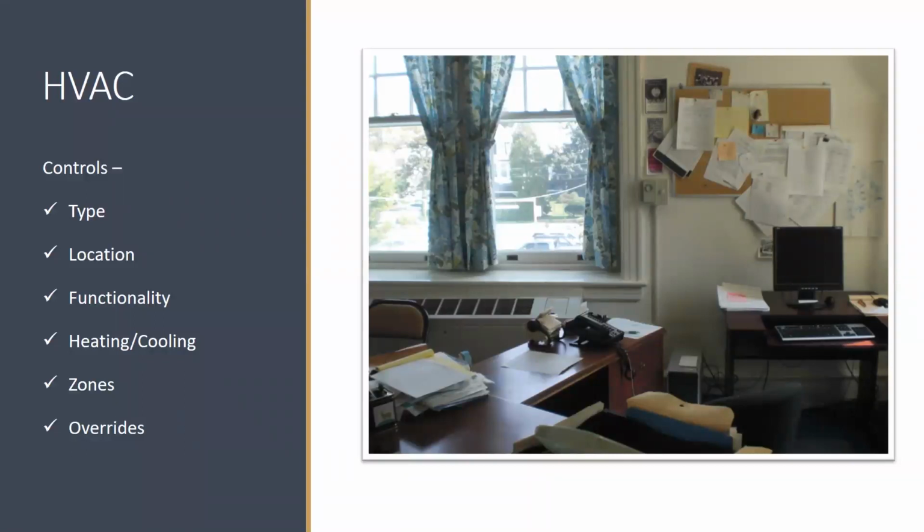With your HVAC system, let's think about your controls. The thermostat, for example. Do you have multiple thermostats? Are they possibly overlapping due to doors? Have you remodeled and therefore changed the size or location of rooms and types of rooms? Make sure the thermostat is not in a place close to a heat source or behind things that will impede their ability to sense the room temperature. Is it on an exterior wall?